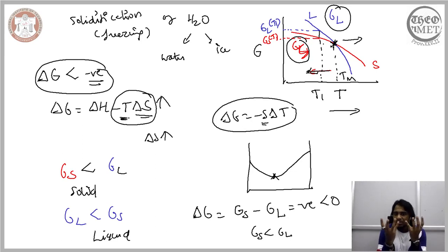So what this discussion helps us do is, thermodynamically it has now become possible to discuss the driving force for the change in the state of the system through the Gibbs free energy, and how much driving force, through this plot here. So this is the first step towards identifying which state or which phase, solid or liquid in this case, would be stable at a given temperature. We will build on this understanding, and we will see what more we can gain from this representation or this discussion on which phase will be stable at a given condition.